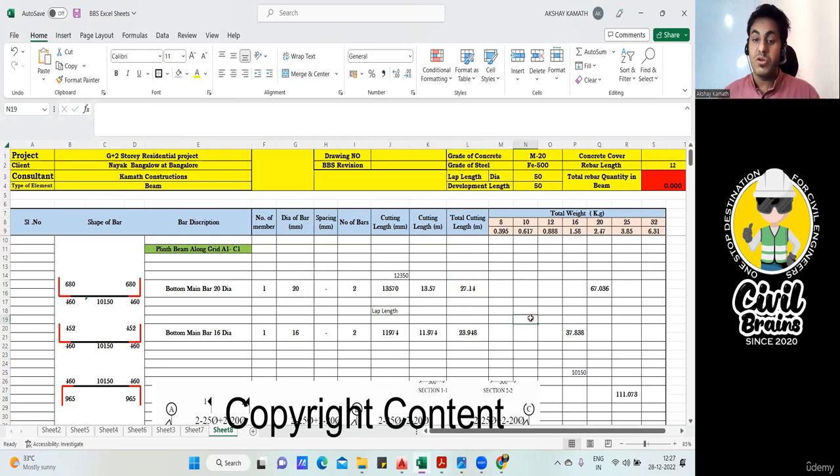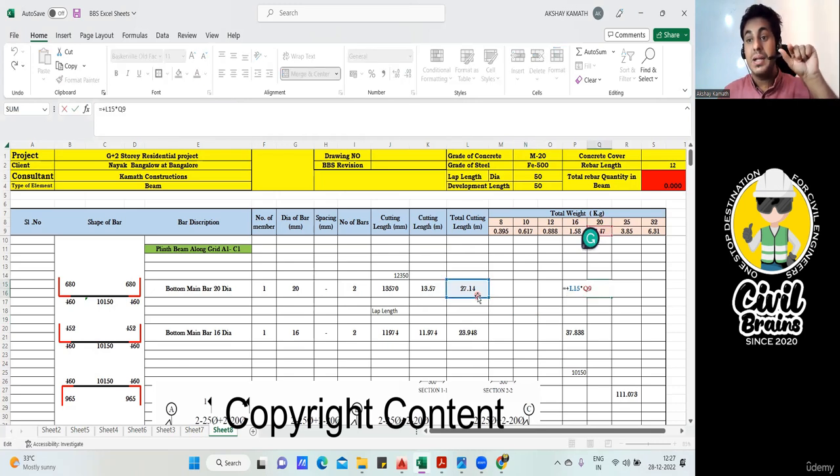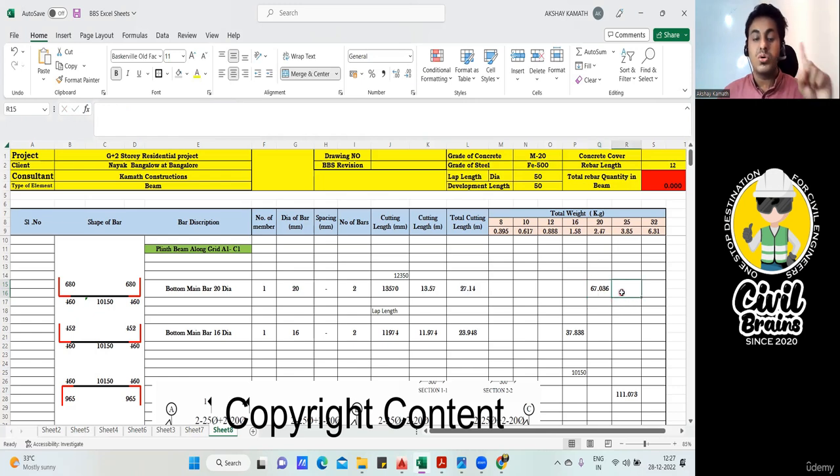Now I need to find the weight of the bar, right? Since I'm using a 20 diameter bar, I need to go to the 20 diameter column. I'll click on 27.14, which is the total cutting length, and multiply this by the unit weight of 20 diameter, which comes out to be 2.47. You multiply 27.14 into 2.47, you'll get 67.036. So this is the total weight required in your bottom main bar of 20 diameter if you're using two numbers. Okay, clear? This much you have understood?